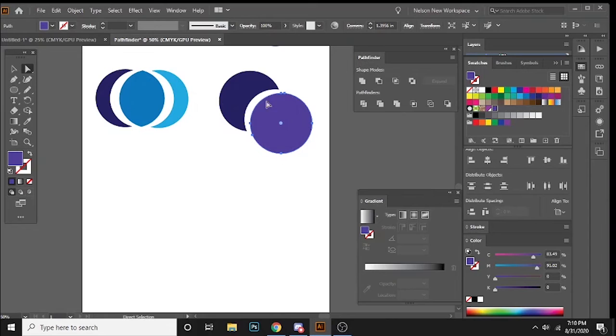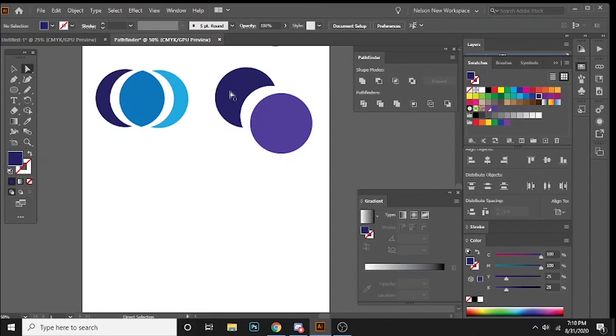So use the top object to trim a piece off of the bottom object. So if you wanted to draw a moon like crest, instead of trying to figure out how to draw this shape, you could just draw 2 circles real quickly and use the trim option to make a crest.